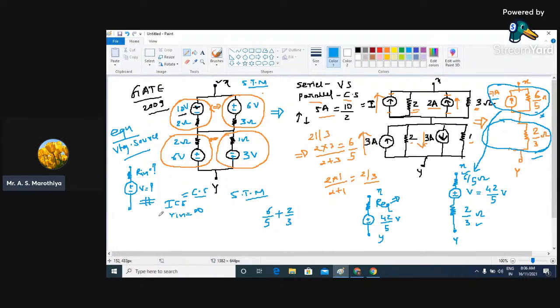In the same way, we know that the internal resistance for an ideal voltage source is nothing but 0. So whenever we want to find the equivalent resistance in a circuit where we need to ignore a voltage source, we are going to replace it by short circuit. This is very important. So an ideal current source, we need to replace by open circuit. In the same way, a voltage source, we are going to replace by a short circuit.